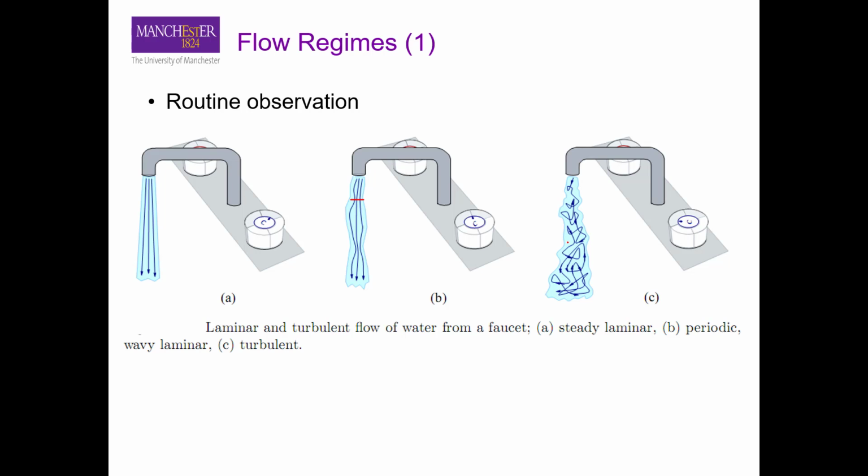Okay, so we can characterize these three systems here. We call this system laminar flow, where we have much more straight streamlines without any intermixing. And then we have the other extreme where we have completely disordered streamlines, and you have a lot of intermixing between the fluid particles, and that's what we call turbulent flow. Okay, and in between these two extremes we have a region that is called the transition region, for example, if you are transitioning from laminar flow to turbulent flow by increasing velocity, or the other way around.